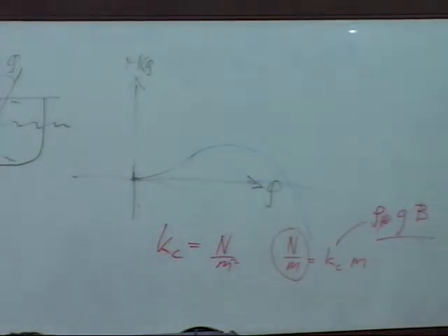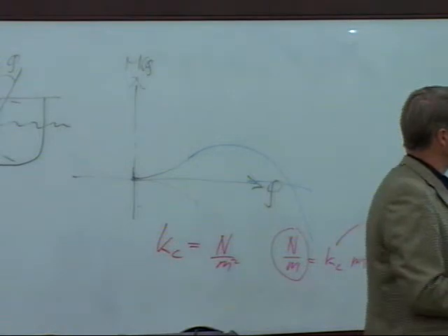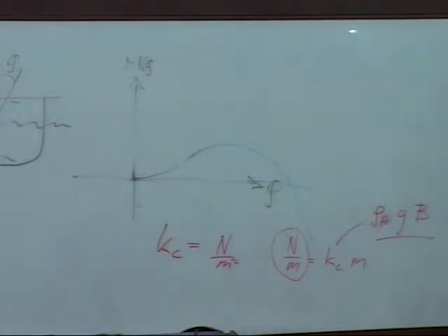But anyway, if you solve this problem analytically with a differential equation, you'll find that if you apply a force, it will bend, and then you'll have an inflection point where it goes from a positive bending moment to a negative bending moment. That inflection point is what is called the characteristic length. It's not really correct in this drawing, because the inflection point, where the moment is changing sign, is not out there. It's somewhere here.